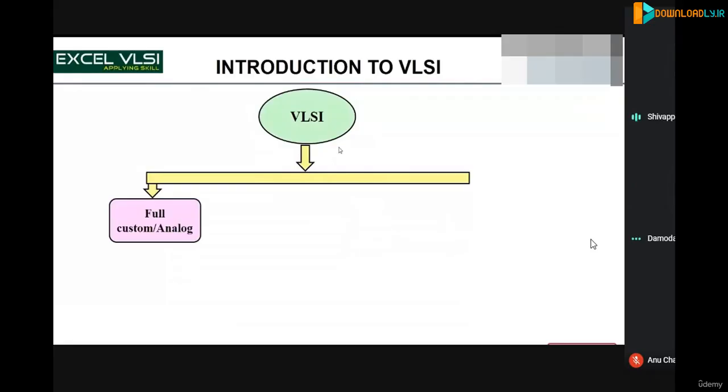Okay, so in VLSI there are three categories. One is full custom, which includes both analog and digital. That is full custom VLSI device design. Here, right from scratch, we build everything. The transistors we design, the transistor characterization we make, and after that we use those transistors for the gates, the building blocks of the gates.